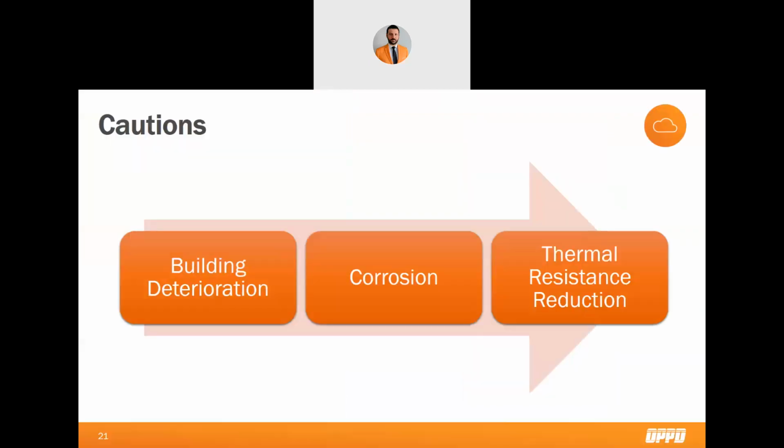Moisture condensation and its mitigation is important when it comes to our homes because water can lead to a building deteriorating over time, not to mention also by biological pests being drawn to the moisture. These pests also have a dual threat of posing serious risk to respiratory health. Water, as we know, will eventually corrode metal. It can also dissolve any glue that is used in construction materials. Water and moisture can slowly but surely warp wood and even weaken mortar.